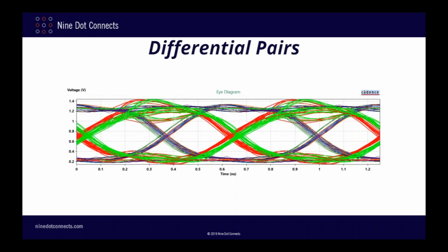And if we look at them in the eye diagram, we also don't see anything that really should worry us. So the takeaway here is that mismatched trace lengths within differential pair routing have a far greater impact on the design than do the length tuning wiggles needed to match them up.